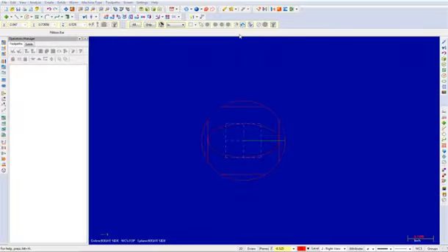Now we will create 2 arcs and then rotate them around the diameter. Select the Isometric Graphics view from the toolbar. We must change the construction mode to 3D in the status bar. Now choose the Create Arc Circle Center Point command and input a radius of 0.125.